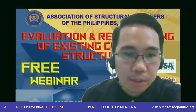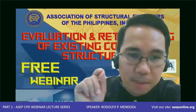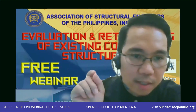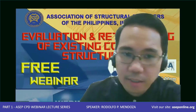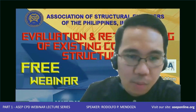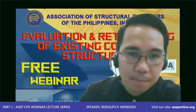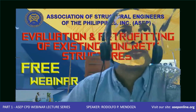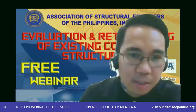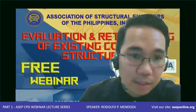It is important to note that when you develop these drawings, you must specifically put in the drawings that these are as-found drawings, and they are not as-built drawings, and definitely as-built drawings will never be the same as as-found drawings. What you need to do is declare to your client that these are the basis that you use in evaluating their structure.